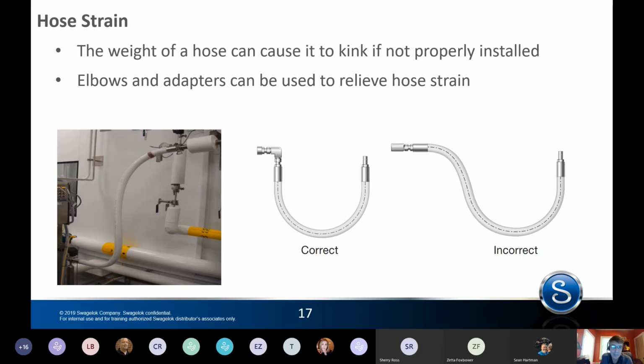This is done most often because a port or a connector is coming out horizontally and it's being installed on a different horizontal plane or vertically, and the installer doesn't want to have the cost of an elbow. And so because of the cost save of an elbow, this hose is being stressed and fails much faster than what would be expected.